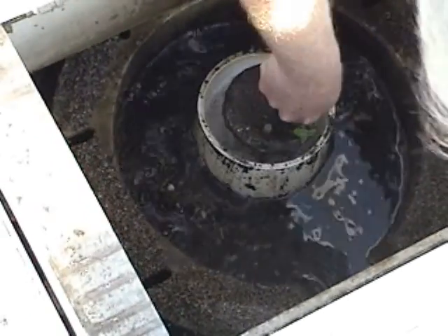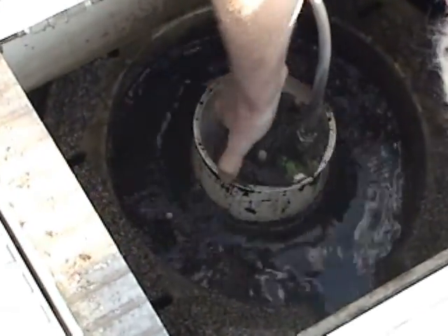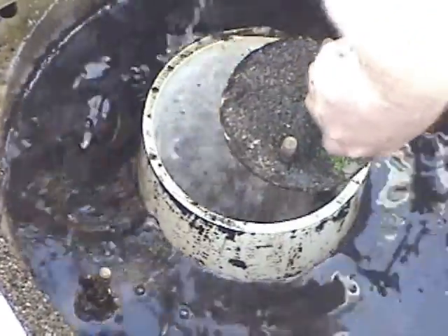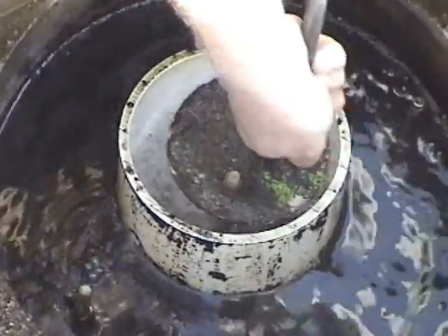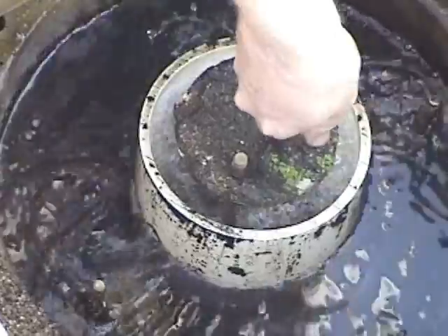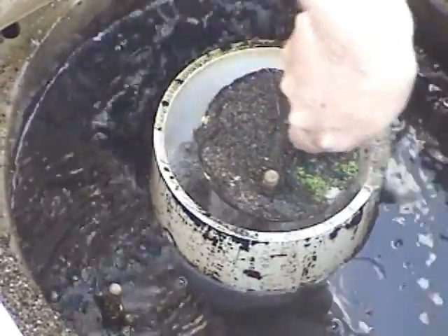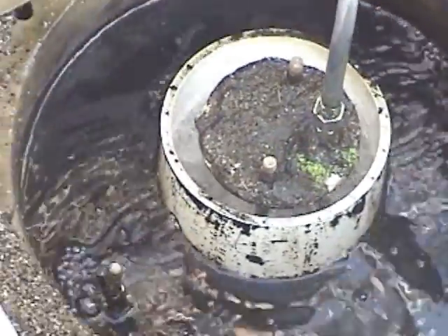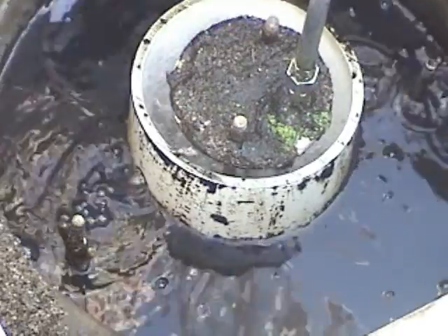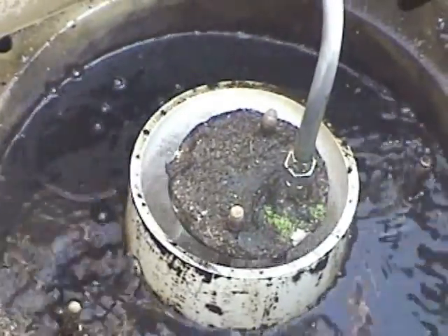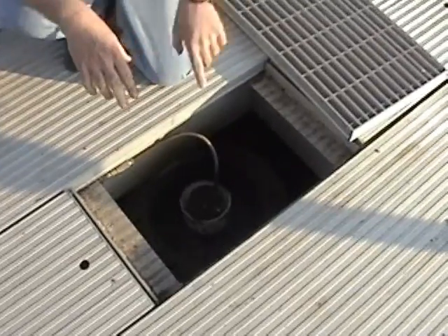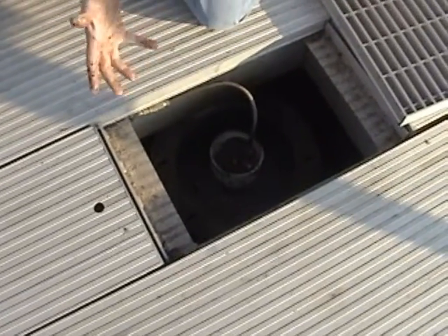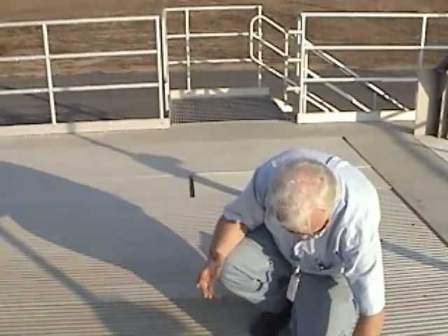But when it gets to right in here, you want to make sure that that is sitting in the tube properly. That's good. But that's the only thing, it will drop all by itself just like it did right there. But when it gets to the bottom, it sits in a cylinder, and you want to make sure that that barrel fell right in that cylinder. Because if it's sitting on top, it won't pump sand, which when it's not pumping sand, it's not filtering. So to answer your question, they pretty much go in all by themselves.